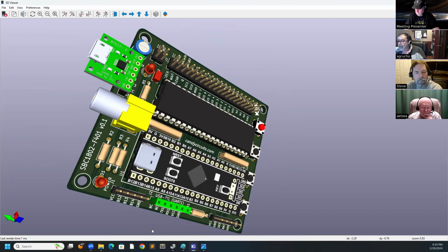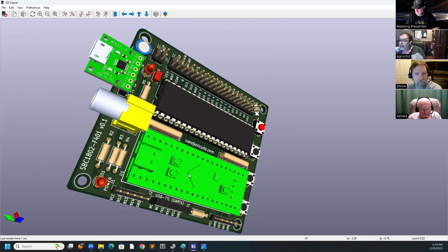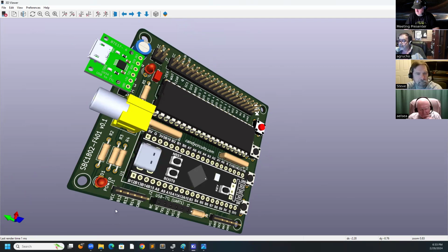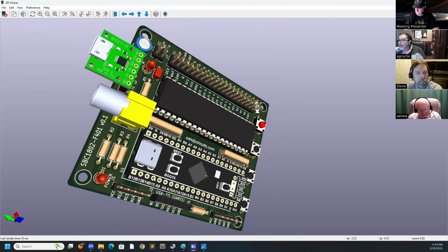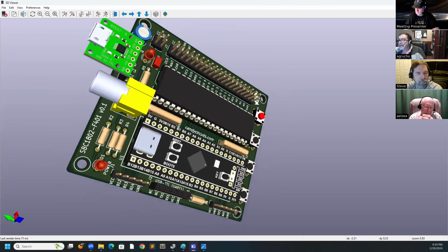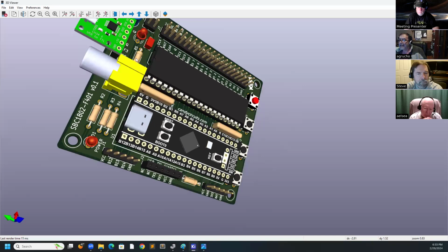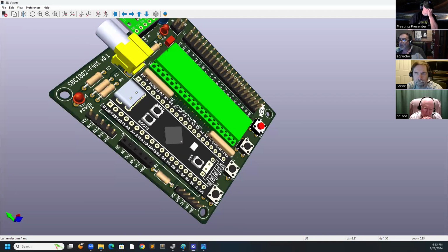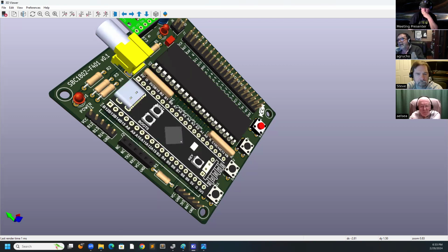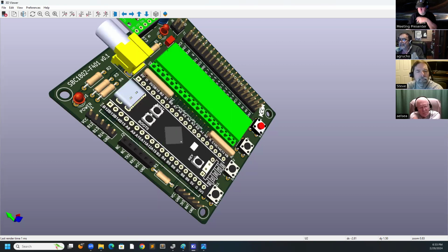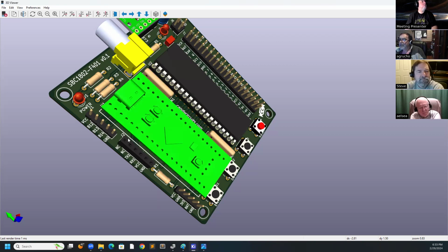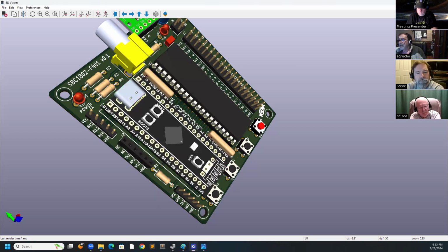I am using a modern, fast microcontroller. The microcontroller checks the address lines and the control lines to feed the microprocessor with data depending on what address it is accessing. And I am doing this in assembler code to do it faster.